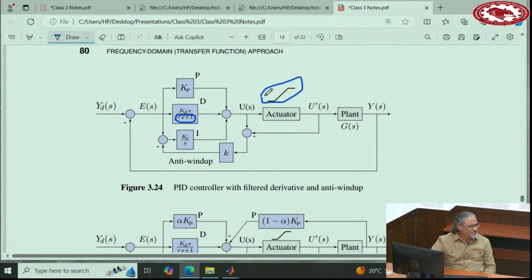It saturates. So when it saturates the output, during this extreme mode that sometimes happens in physical systems, and we will see in converters also it happens a lot, during this mode, the integrator starts growing the output without really having any impact on the system, because it's in saturation. But the integrator keeps integrating, and the output of the integrator winds up, goes up, up, up, up. Now, when the system eventually, assuming that the system is stable, comes back to the linear mode, it takes a long time for the integrator to wind down. So the system will start oscillating with large and long oscillations.